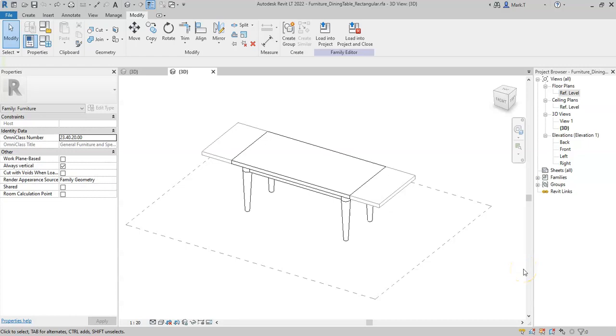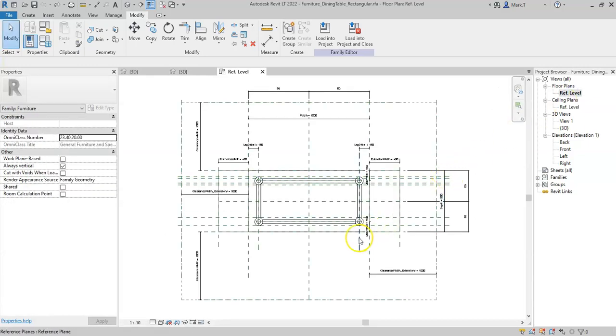Revit has the capability to load or nest other Revit families inside families. There are a number of benefits to doing this. It reduces the complexity of the individual family by building up separate components and loading them into families. As we have seen, during the creation of this family, the number of reference planes and dimensions can become overwhelming, especially if you want to come back to edit it later or expect someone else to use or edit the family.